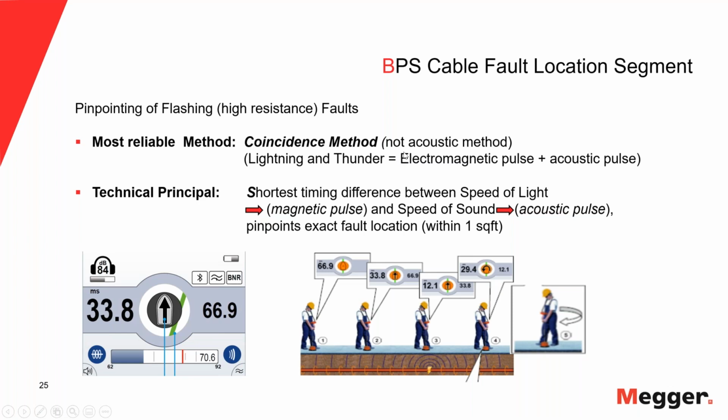So it basically measures the time for the sound to get to you, because the thunder, or in our case, when we fault locate, the electromagnetic pulse from the flashover will travel with the speed of light. We cannot even measure this. But we can measure the time it takes for the sound to get to us. And so you can say this type of pinpointer is like a stopwatch.